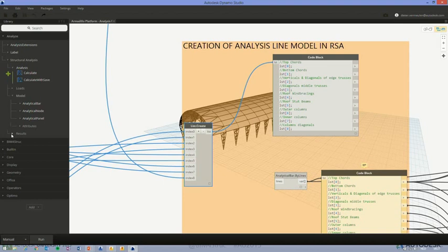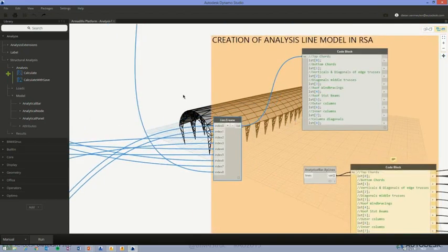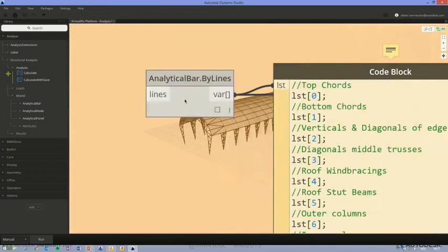The Revit ID should be maintained, so it should not create a new object. That's the way Dynamo and Revit communicate with each other. If you open the same script 3 days later and work on it again to regenerate everything or make some changes, in the background it knows which Dynamo script has run on top of it, and it will remember that Revit ID.